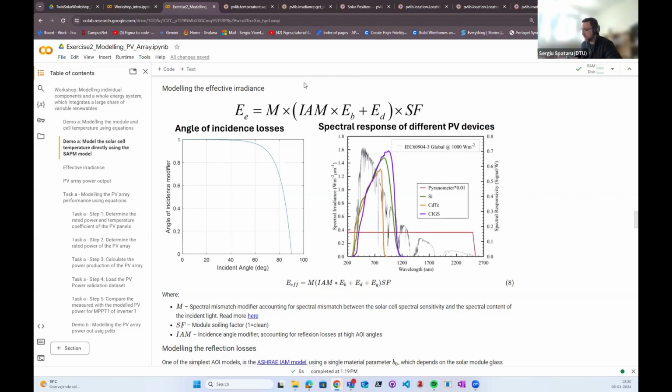of soiling because you have quite frequent rains, although you have a very low tilt. So when you have a tilt of 9 degrees, dust tends to accumulate. So if it doesn't rain for a few days, you might have dust accumulating on the panels. And this is a problem for more desert areas near the equator or where you have low tilt angles, but you also have a lot of dust and not a lot of rain. Then you need to account for the soiling factor. For Réunion, that is not the case as far as we've seen.